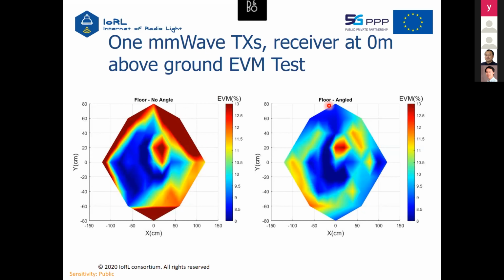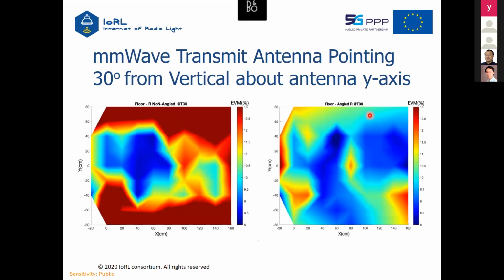Similarly, now if you point with angling, this angling will improve the multipath effect. You can improve with the angling, but you still have this pattern inside your antenna at a central point, even with angling. So this is 30 degree. From 30 degree, you can see this is the positioning over here. At 30 degree, you can see the coverage will be slightly longer along this range. And you have a lot of reflection over here.